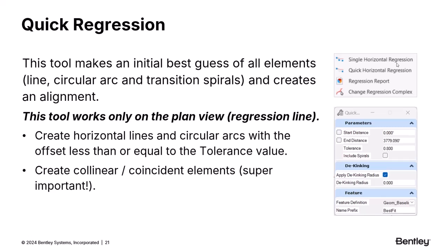the regression line in there. You don't need a curvature diagram at all. It's only going to work on the plan view in the regression space. And it's going to create regression lines. It's going to create arcs that fall less than or equal to the tolerance value that you set in the dialog box here. So depending on your data, you're going to have to play around with the tolerance value to get it to give you what you would need.